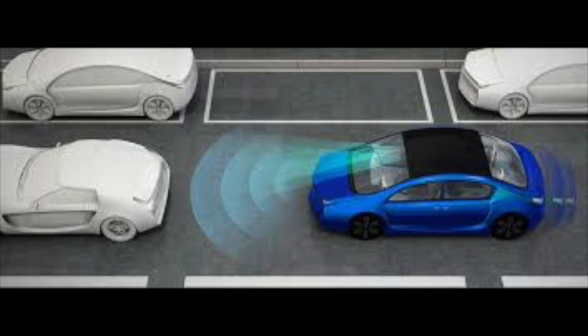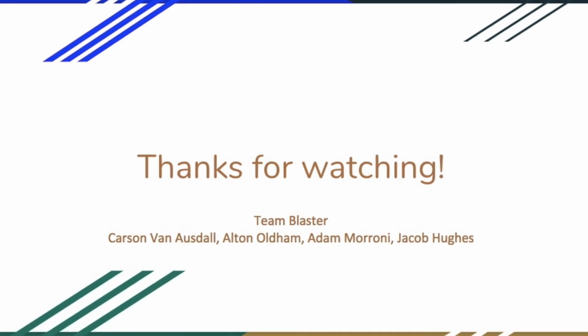Overall, all of our driverless car system requirements for controlling velocity of the car will be met with the plant. We will achieve a rise time of approximately 1.79 seconds, a percent overshoot of 1.71%, and a steady state error of approximately 0%. Our system will be safe, stable, and efficient.